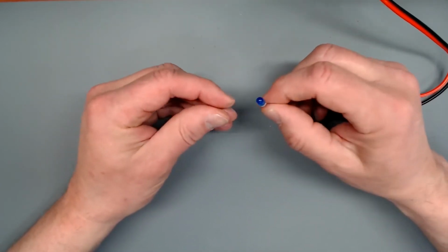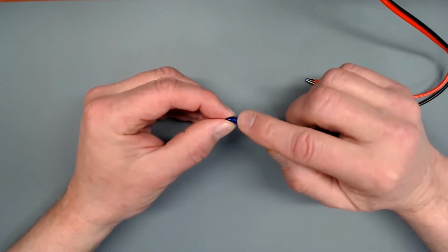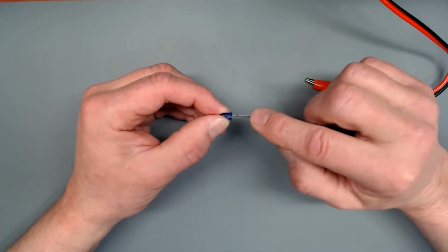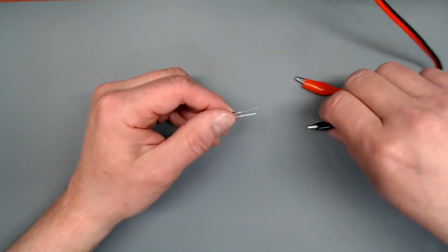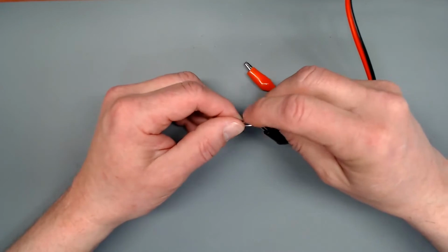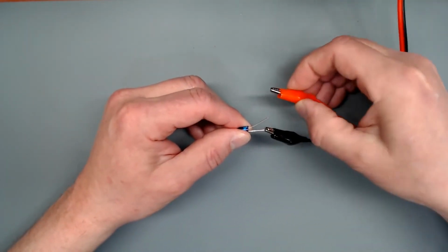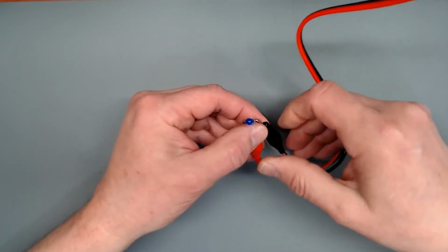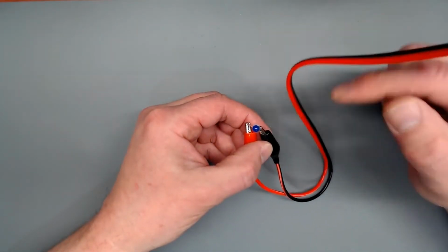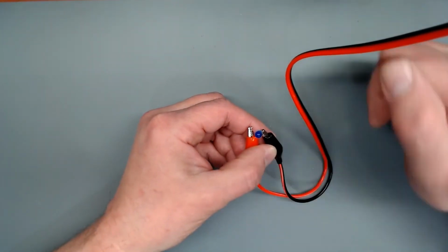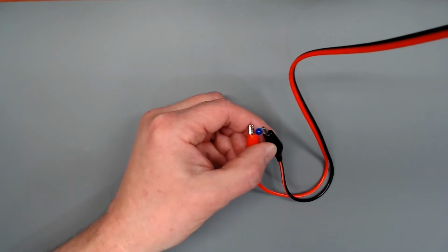An LED of this style will also have one side flat on this little flange area here. And that will be connected to the short leg. So obviously that would be our ground or our 0 volt side. Now we can't just hook up voltage like so. At this point I don't have my power supply turned on, but if I were to put anything other than the forward voltage of the LED on here, it's going to blow. And let's take a look at what that looks like when it happens.